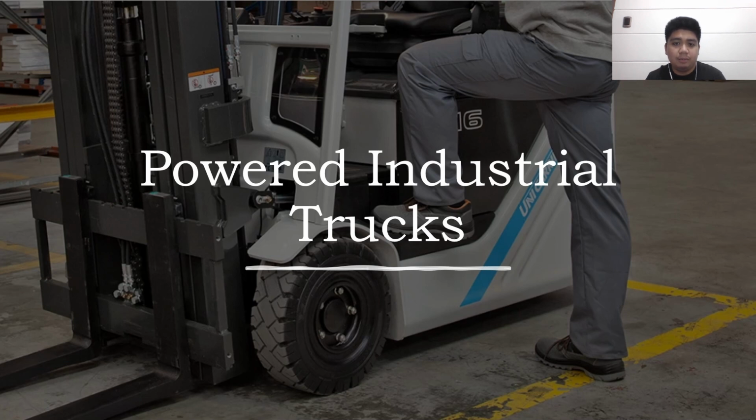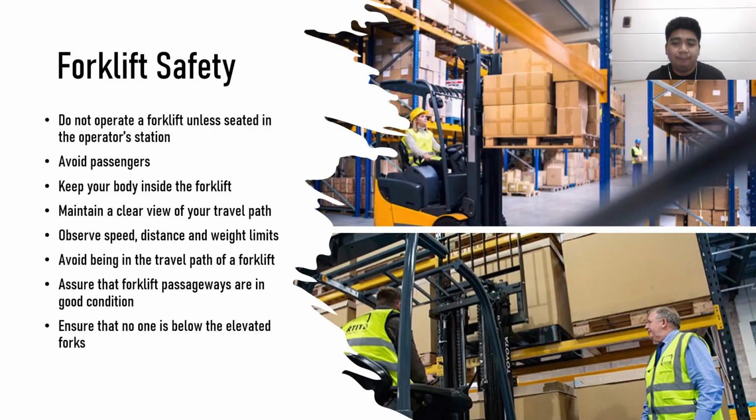However, according to the Occupational Safety and Health Administration, forklift incidents cause serious injuries and fatalities every year. Most often, it is the driver who is killed when an accident occurs. With this, when operating a forklift, you and your employees must consider the following safety precautions. First, operate a forklift only while in the seat or operator station. It is important not to start or operate the controls while standing beside the forklift.